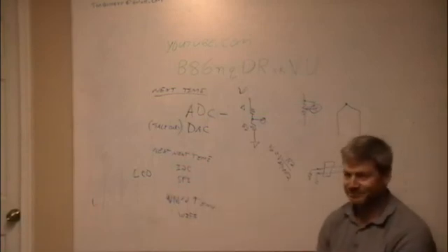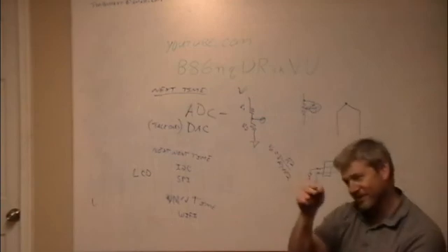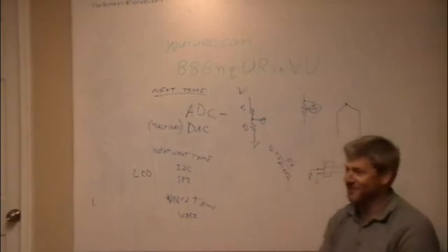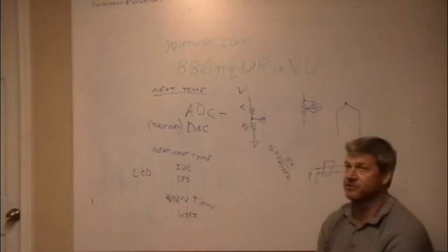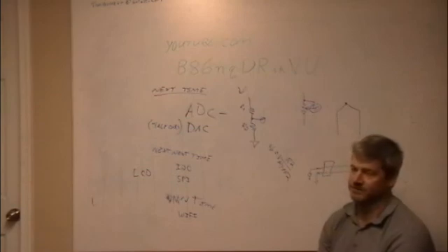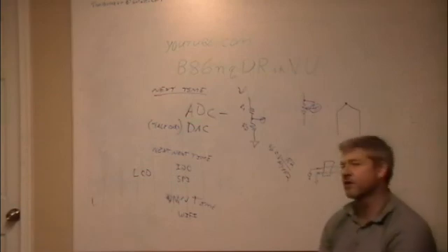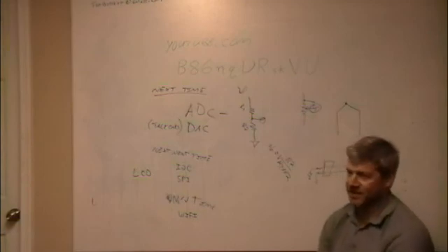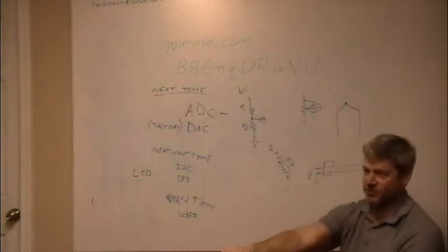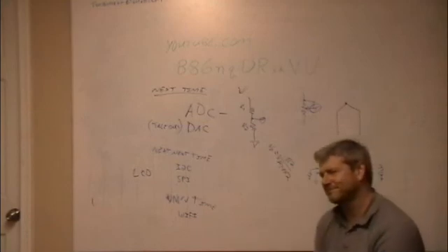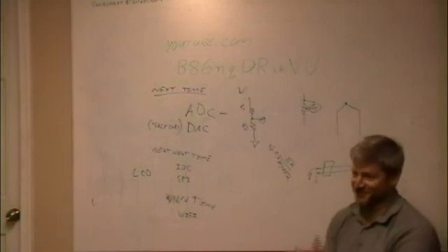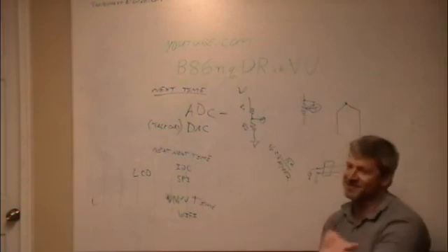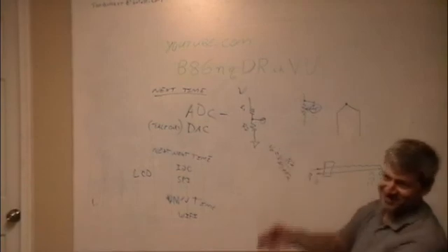It's got a J-type and a K-type thermocouple input, so you can just choose this one or that one. And multiple thermocouples? The one I bought can handle 2 separate thermocouples, but it only reads one. It can be used with a J or it can be used with a K, and it has one single process control temperature that it listens to. But if I wanted to put 6 J-types? Well, on this one, you'd have to buy 6 of these things and control each one separately. So then maybe it makes more sense to go do this. I don't know.